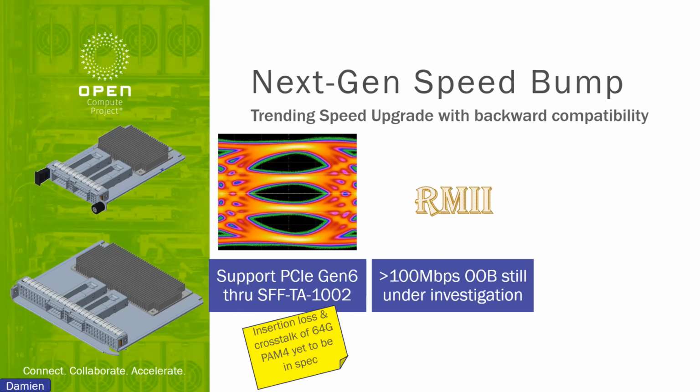The reason is that to support more than RMII, we can go to either maybe RGMII or SGMII, which either have the challenge of more pins that's not backward compatible, or we don't have enough pins. We are looking at tunneling feature as well. But very unfortunately, our pin definition only supports USB 2, so we don't even have USB 3 to tunnel the RGMII capability.